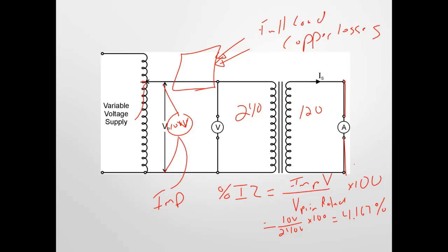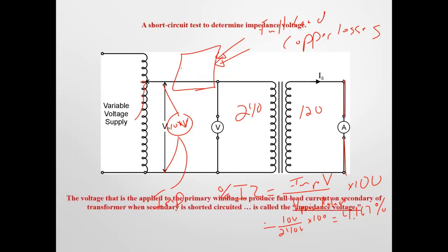Well, we have to purchase and install overcurrent devices that can safely interrupt that short circuit current. For example, I can have a 15 amp fuse that is rated for 10,000 amps, which is our standard rating, or I can buy a 15 amp fuse that's rated for 200,000 amp interrupting capacity.